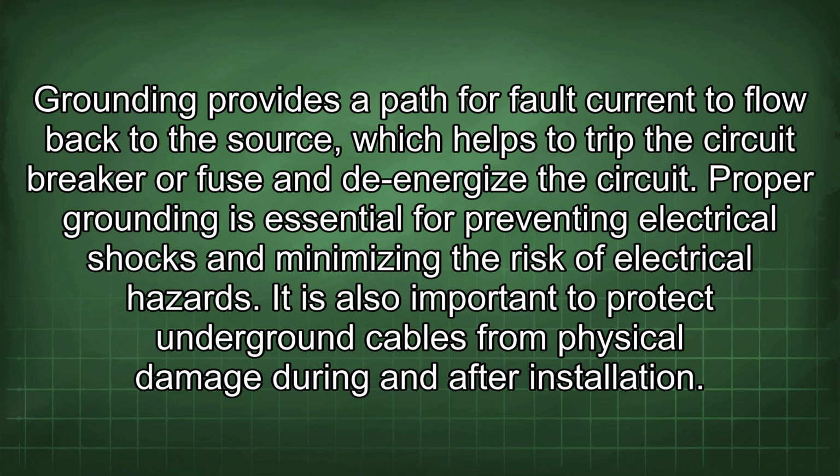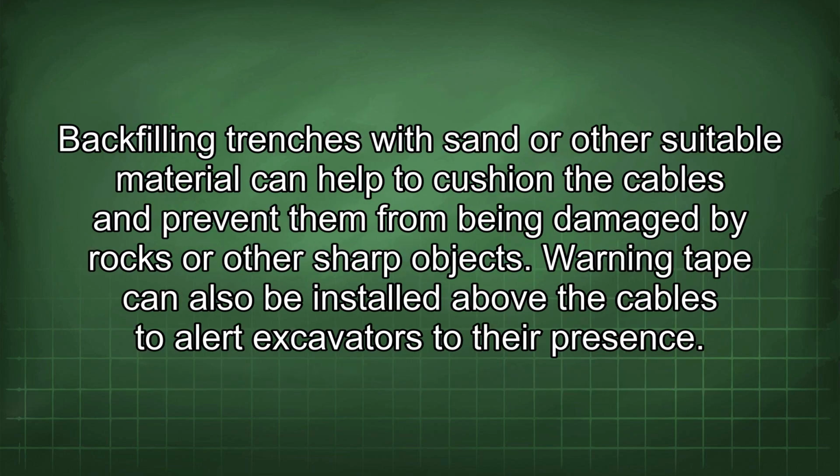It is also important to protect underground cables from physical damage during and after installation. Backfilling trenches with sand or other suitable material can help to cushion the cables and prevent them from being damaged by rocks or other sharp objects. Warning tape can also be installed above the cables to alert excavators to their presence.